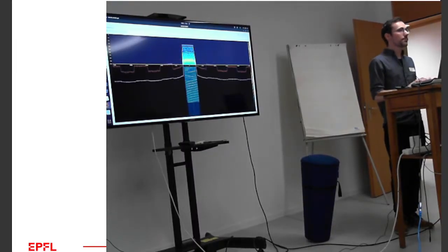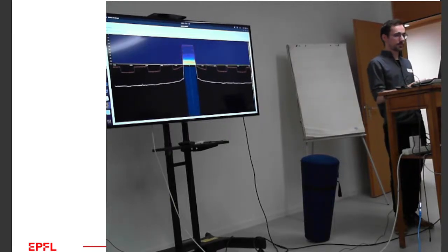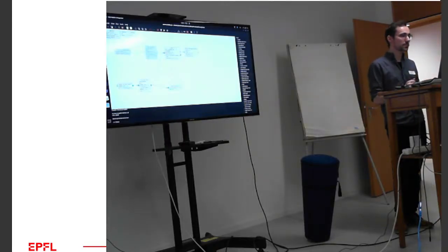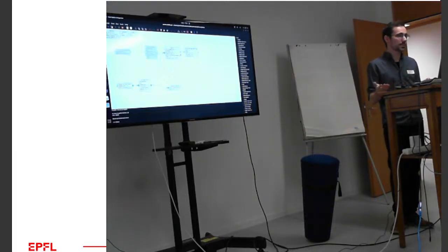So these blocks that you say you can install, do they have a library? Yeah, GnuRadio has a web page with all the different blocks that have been somewhat tested or that are used, and installing them is relatively straightforward. It's made for making and sharing blocks, so it's five lines you type in the terminal to download the library, build it, install it, and then the block will just appear. For example, this is the block that makes the nice visualization.